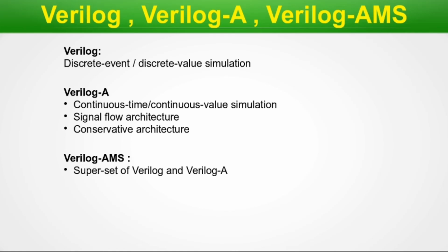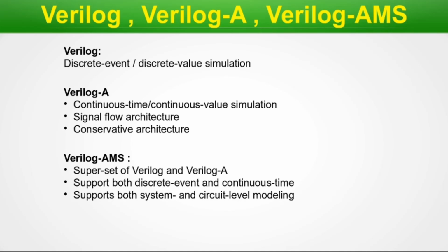It is a superset of Verilog and Verilog-A. So the Verilog we know from the beginning and the Verilog-A that is used for analog, when combined together, no, not combined together, the Verilog-AMS will have something more. Support both discrete event and continuous time simulation. So in Verilog we have discrete event and in Verilog-A we have continuous. So both features are there in Verilog-AMS. Supports both system and circuit level modeling.